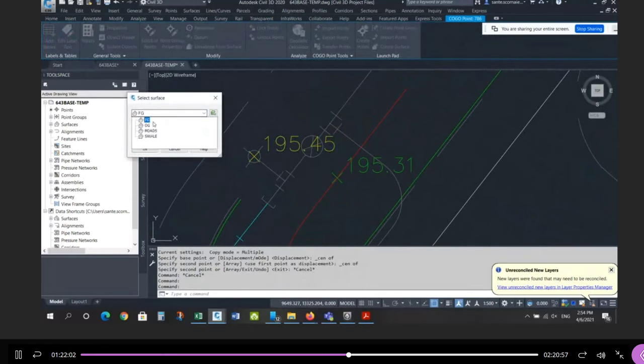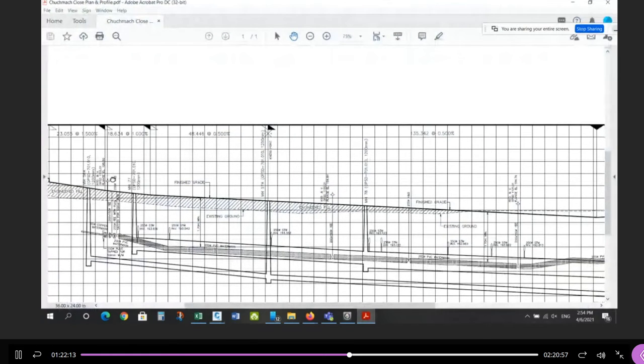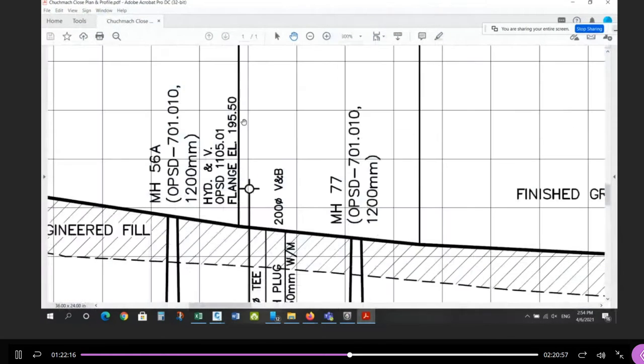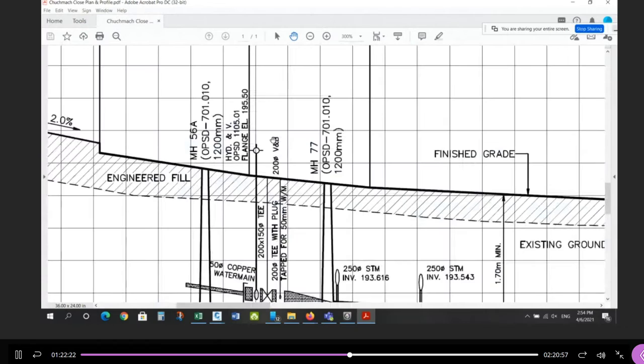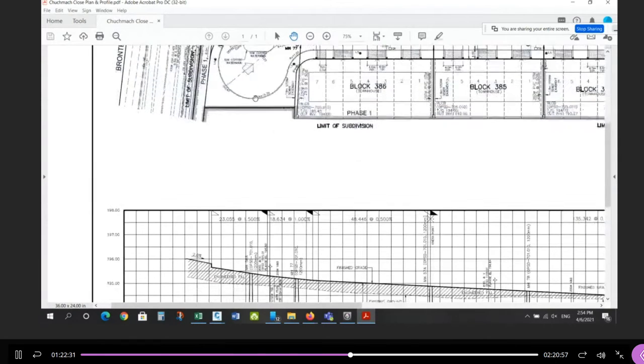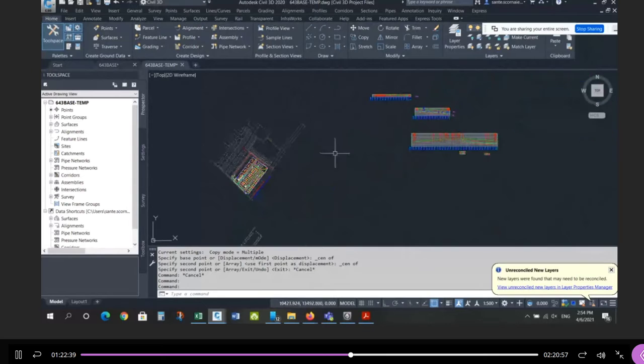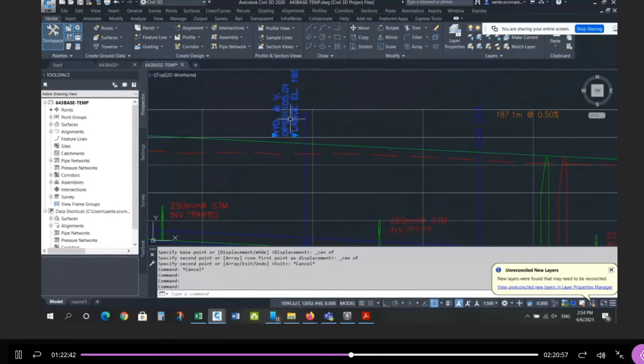Elevation from surface, use the road. So if I add 6 inches to that, 41 plus 15 should be 56, 556. That's this hydrant over here. 550. So it's off by about 6 centimeters. Okay, but we did change the road profile through here a little bit. Remember, this is now not relative to this road anymore, but it's close. That's how it's done. Okay, so that's the technique. What's the flange elevation? The boulevard elevation of the hydrant plus 6 inches, or 0.15. So you need to do that for all your hydrants. You got to do this 4 times.